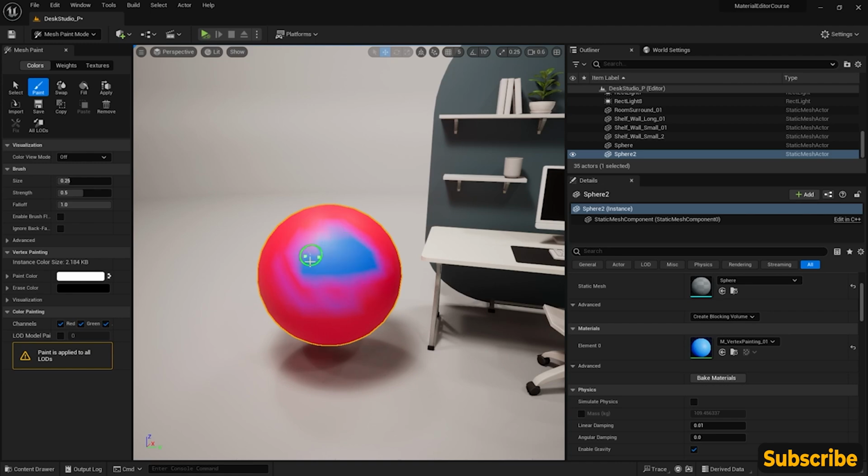If I keep painting it out, you'll notice that the vertex painting resolution is dependent on the number of vertices. If you notice very carefully as I move around, these little green dots appear. Each one of those green dots represents a vertex, and so we can only paint a particular point. If we only have a bit of information here, but not much here, we're going to interpolate or find the average of the two colors, which gives us this purpley edge between the two vertex colors, which can be kind of helpful. It gives us this softening look.